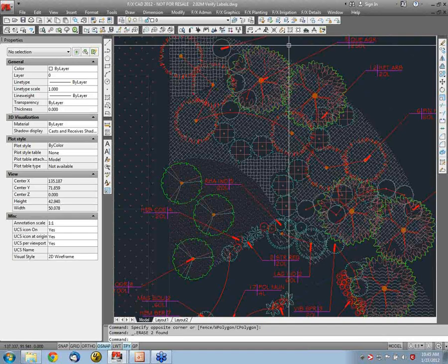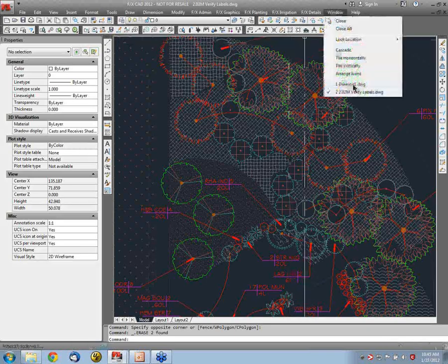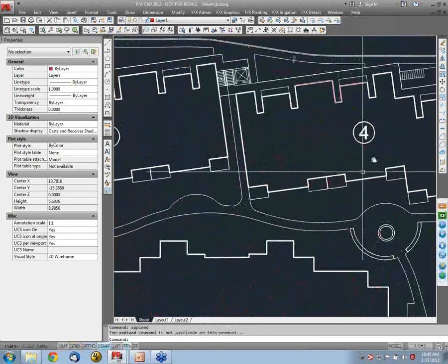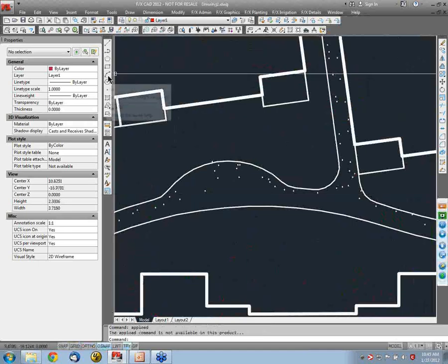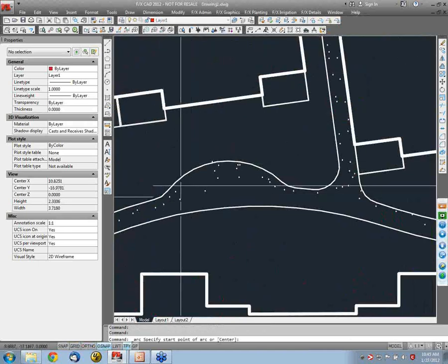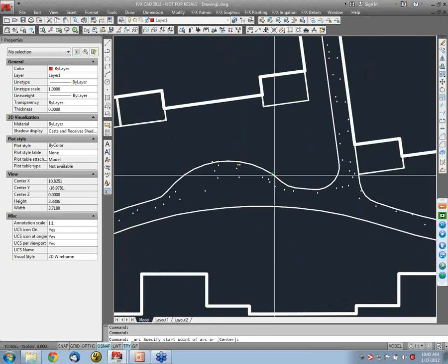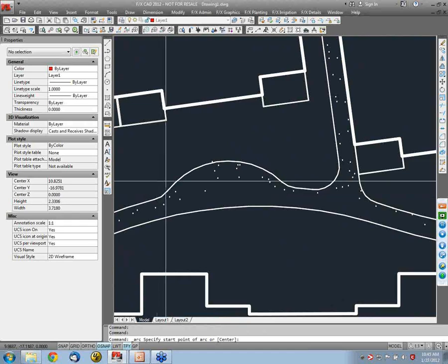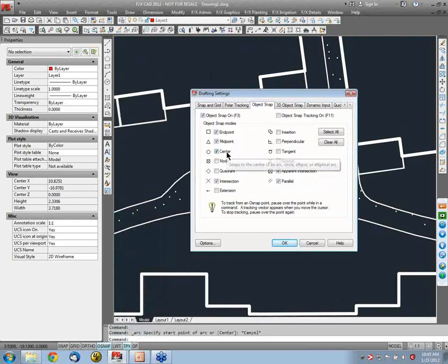One more thing on the PDF, if you could go back to that, is can you trace arcs? I do have some arcs in that particular drawing. You can see one right there that should be an arc, which is how those were created. So you could go to the mid, center, and the end of the arc, then the center of the arc, and then the other end of the arc to draw and mimic that particular arc, it would seem to me. Exactly.